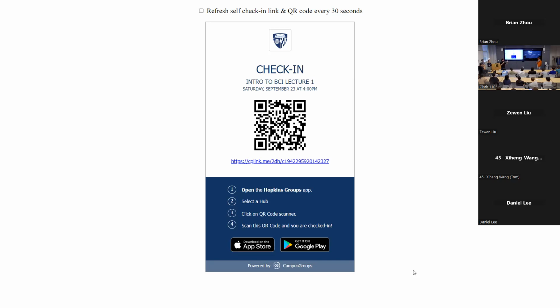So the signals get picked up here. It's sent here. You can then hook it up to the computer to program it and to actuate it. Say, I haven't plugged it in yet, but you can use that and then say, use your muscles, run the code here, and then you can process the outputs to control a little servo motor. It's a very basic example of how you want to use electromyography for controlling something mechanical.